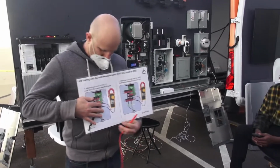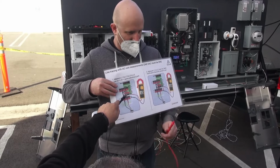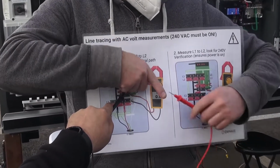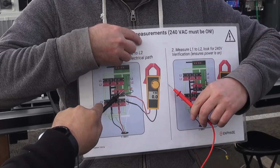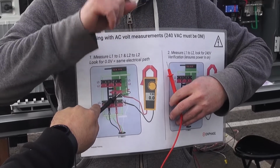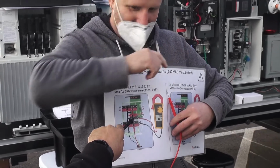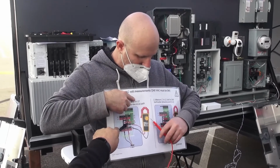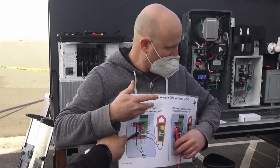Now you have to do something. You have to be careful, because what if I measure somewhere else, like my finger here, this wire? If I measure here and I get 0, I'm like, okay, that's a good thing, right? But what if my coworker over there turned off the power? So you have to make sure you leave that one there, and then you have to measure the other one to make sure that it's live.